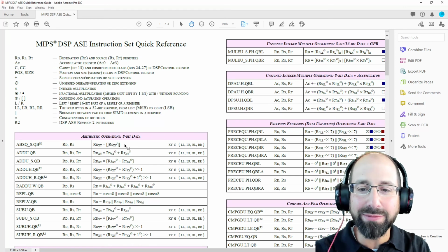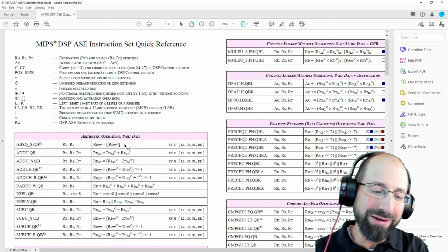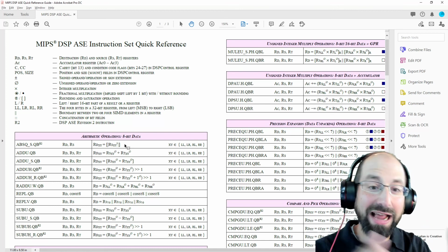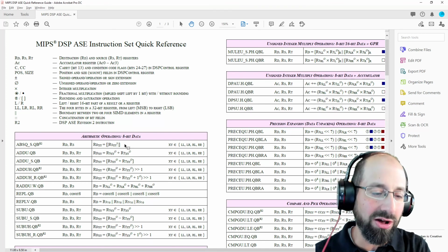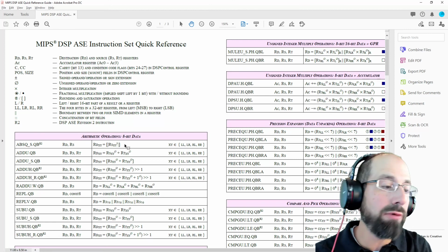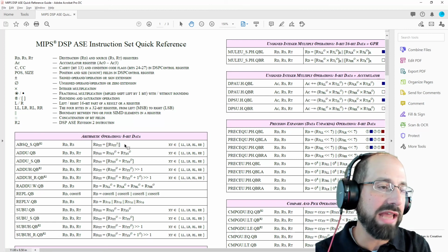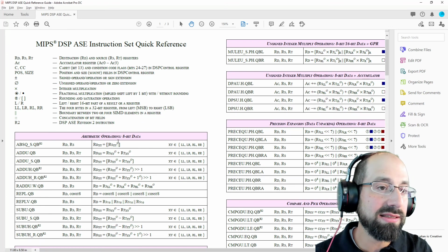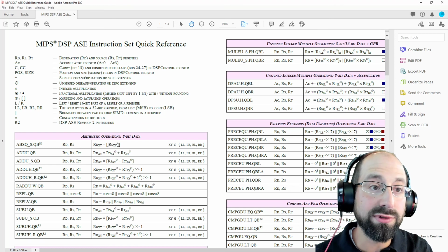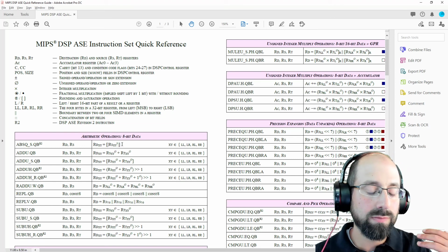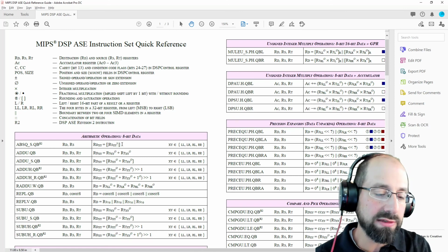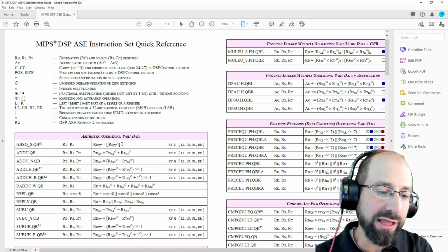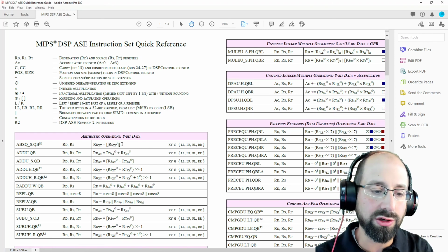Even though I said you can integrate them together, just make them separate so you don't wind up with a broken version of your stuff that was already working, and that can be very frustrating. So copy paste that file, even though you can implement this all into a single ALU and start to play around with adding those adders or those AND gates and muxes. That's ultimately all that's required to implement this. Some constants to do things like saturation and absolute value potentially, some AND gates for the new control signals that would be required, and some muxes to select between different flavors of the same type of instruction.